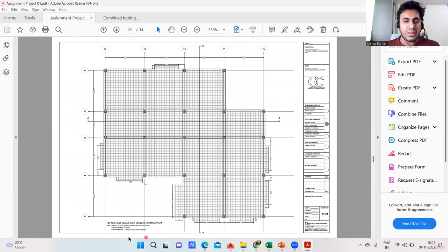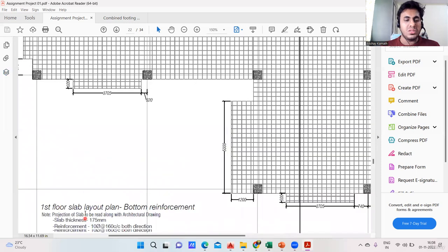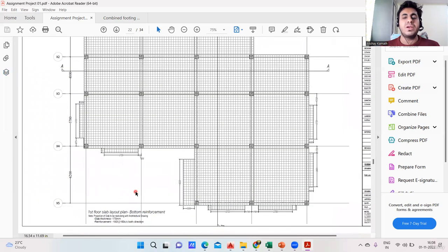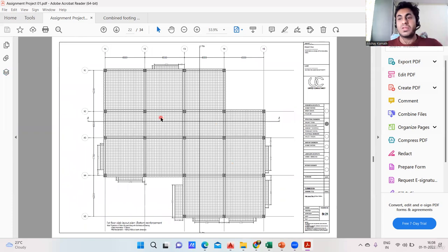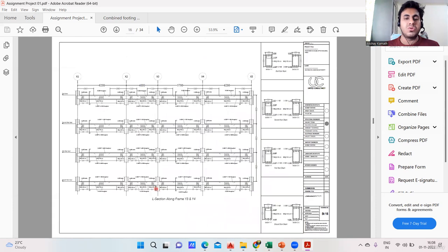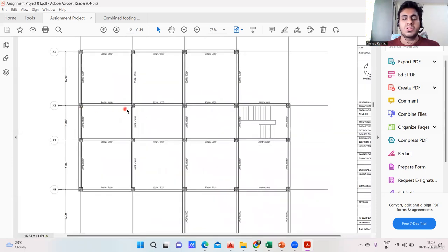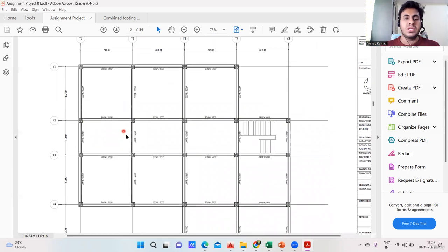So this is your slab. You can see here the slab thickness, these people are telling it is 175. So everywhere it is 175, you can take 175 as the thickness of the slab. And when you want to take care of the inside shuttering, the overall depth minus the slab thickness, which is 175 everywhere. Okay. So in the same way, you can find out the slab concrete quantity also. You know, this much area will be the slab portion. You find the area of that. Okay.